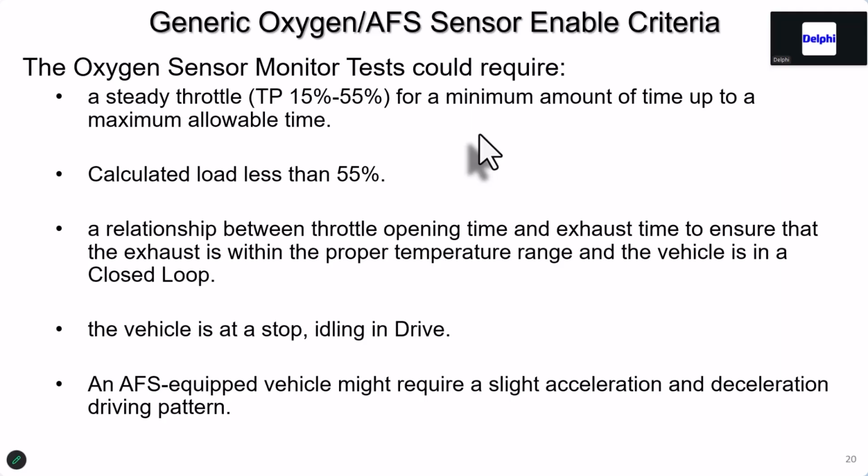Some air fuel sensors, oxygen sensors, will run at idle while in drive. And we're going to see a little later, some might require light acceleration and light deceleration because of the active fuel management. You make it a little rich, you make it a little lean, and you Humpty Dumpty it, as I'm going to show you. And that's how it judges whether the thing is working correctly.